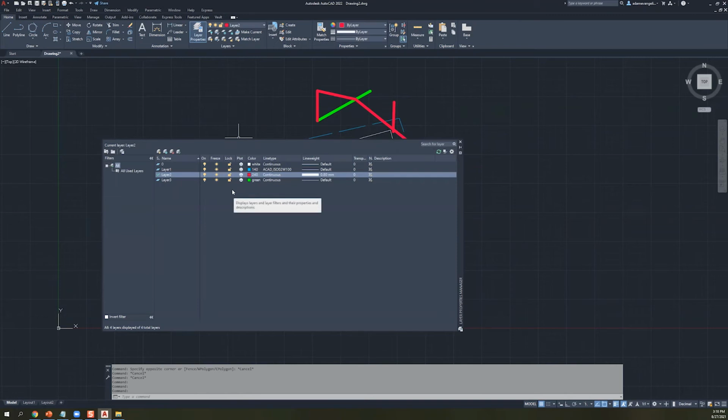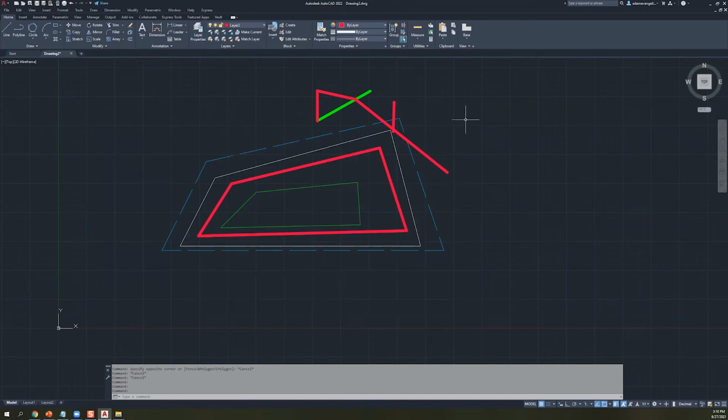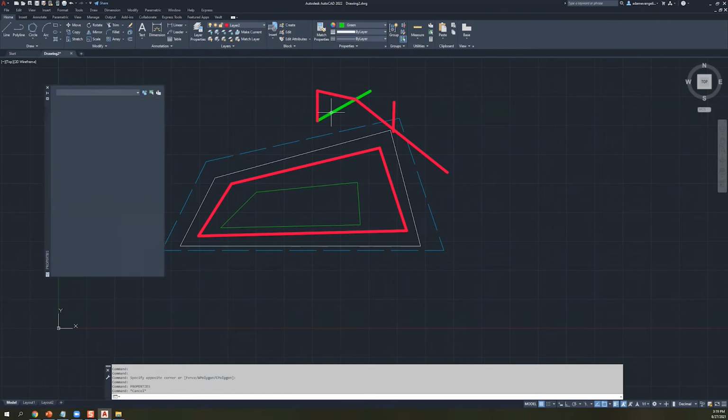That's a really common call that we get as well, where people are like, why is this line green? I set it up so that this line would be blue in this layer. And that's where all that information drives from, right? So AutoCAD is, like a lot of things in life, I suppose, a lot of the preparation you do ends up paying dividends in efficiency later on. So just be aware of that, and you won't have to spend time searching for random stuff like that and errors as you go through and do your work.